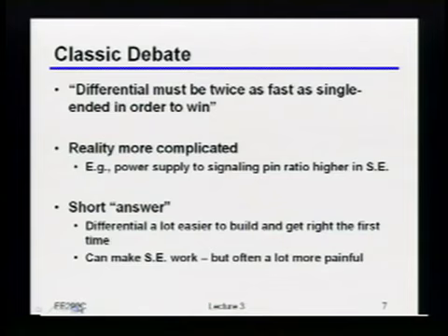Okay, with single-ended, you really have to think very, very carefully about every single little piece there, because if there's any noise source or interference source that you forgot about, it very easily could be completely wiping out your signal. Okay? And obviously, the higher frequencies you go, the more of these types of issues you have to worry about. Okay? So simply for that reason, I will mostly focus on differential signaling in this class. But that's not to say that single-ended isn't an option. It's a viable option. Just, from an engineering standpoint, it takes a lot more manpower, a lot more brain power, a lot more chips that basically are dead the first time they come back in order to actually get it to work the way you want it to. Okay? Does this kind of make sense to people?